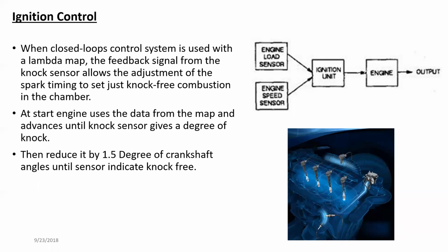While the fuel system is doing all this fuel trimming, increasing or decreasing the fuel supply, that may cause engine knock because of fuel starvation. To make sure the engine is not going to knock, the ignition unit always measures the signal from the knock sensor.